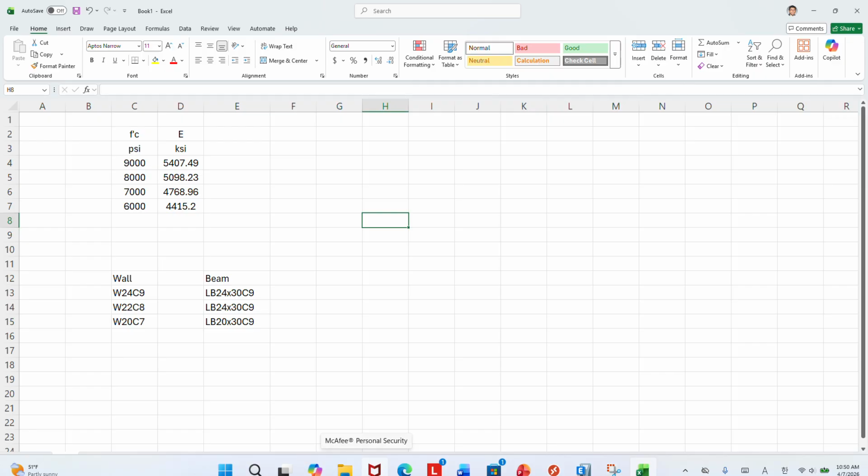And also, since we don't have wall section properties, the default has only 12 inches. So we're going to set this up. Maybe we can do more, but for time restriction, we try to minimize it to only 3 sections. So when you guys open ETABS, I will show you what needs to be done, and I think you can run the model.